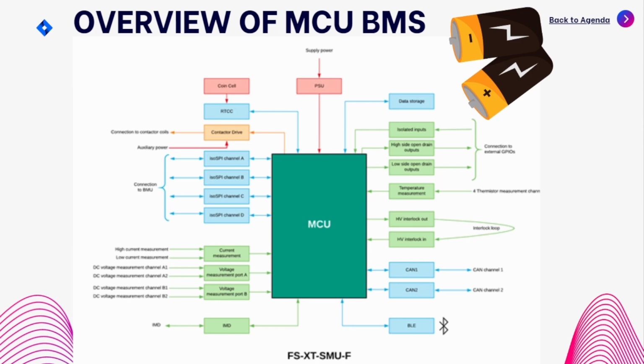Third thing, which communication protocols are required. For example, you might require CAN communication for interfacing between the components of the electric vehicle. Then you might require I2C communication for communicating with the EEPROM or RTC, or some other sensor. You might also require SPI for interfacing with an LCD and the like. You need UART communication for debugging purposes or GSM, Bluetooth purposes.